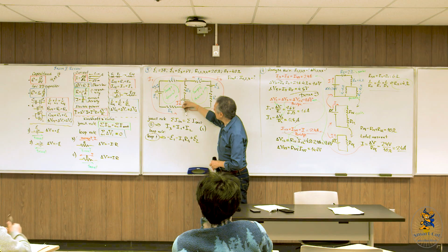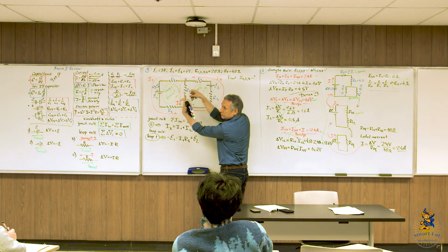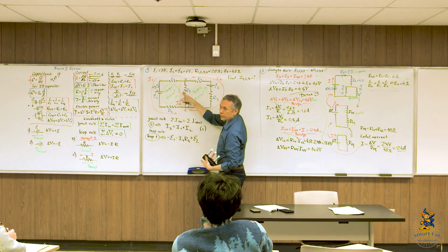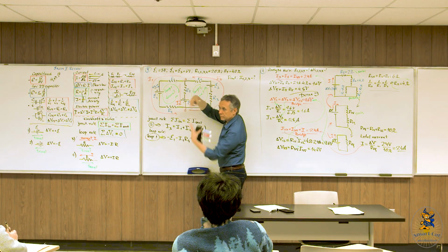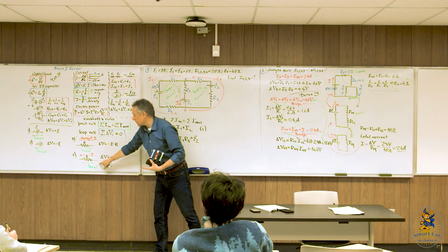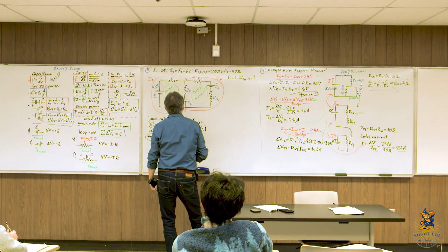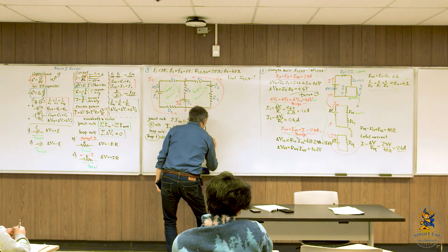The current is down, the travel direction is up. Directions are opposite. When we move up across this resistor, the current I2 is down. Opposite directions, in this case rule number 4. The contribution is positive, so it's plus I2 R5.